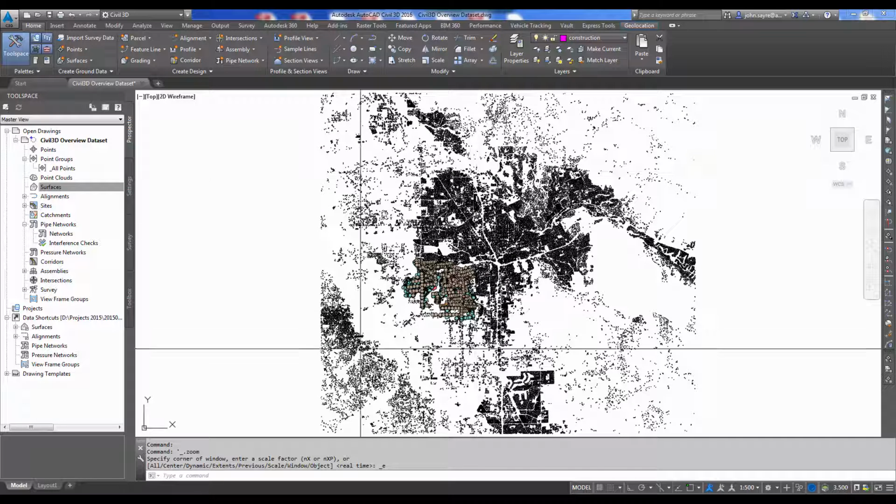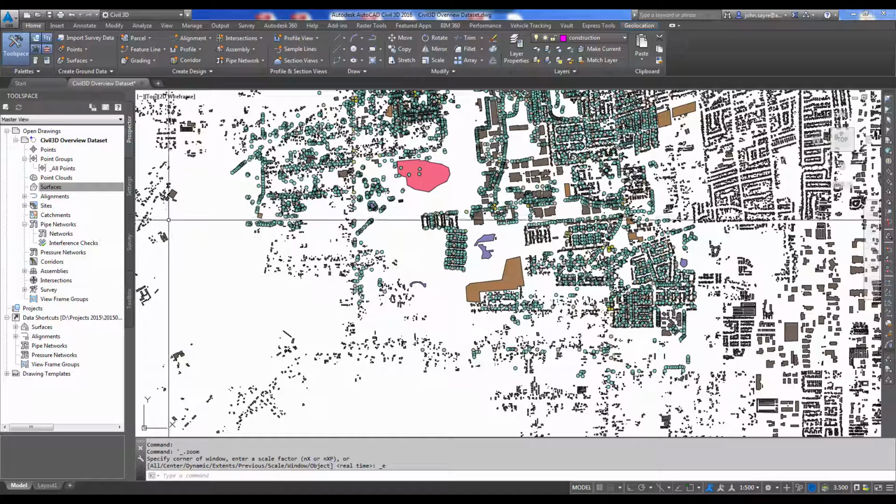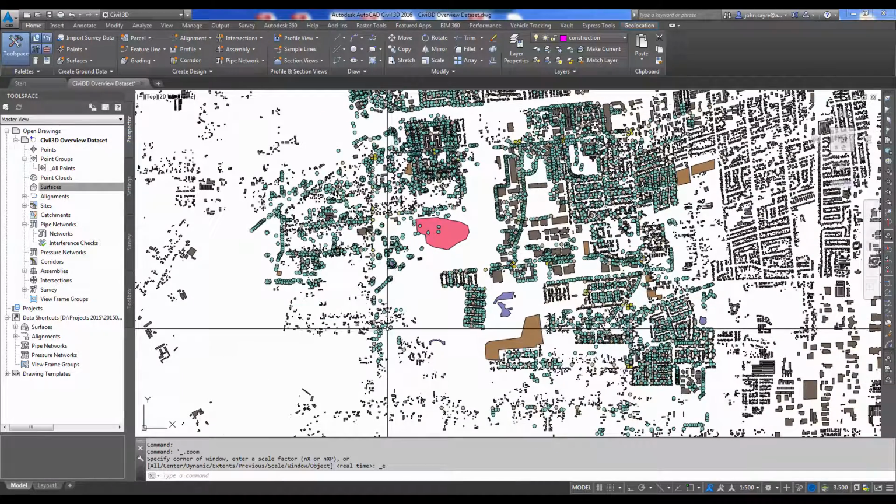Now here's all the information. Now it looks like a lot of data, so we could confine this data just a little bit. What we're really worried about is where the proposed center line is going to be inside of this project. Now, why did I bring the GIS data in? So that we can see if we're going to have problems with running into utilities, going through a wooded area that nobody wants to disturb, maybe actually going through a house. We don't want that. So this will give us a good idea of where everything lays.